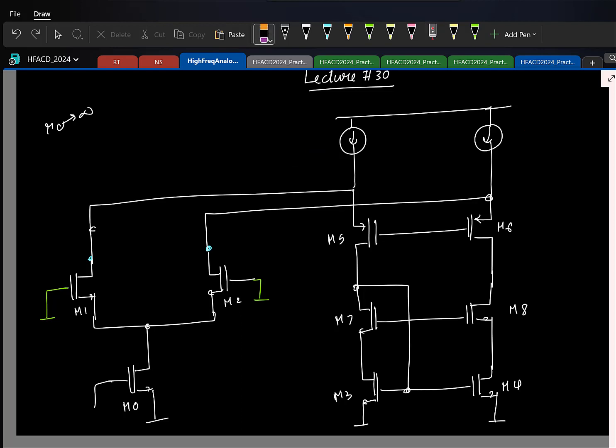We have to replace it with transistors. So if you replace it with a PMOS current source like this, maybe I'll draw it in a different color. This is the only additional set of transistors that we add in a folded cascode compared to the telescopic cascode, right? I'll give it as an exercise. You can work it out. You will find that these will indeed contribute to noise.